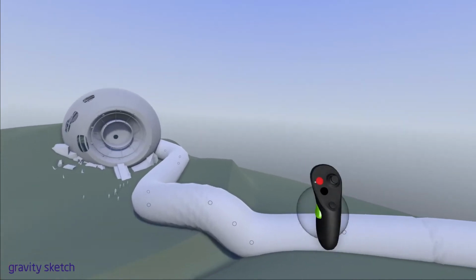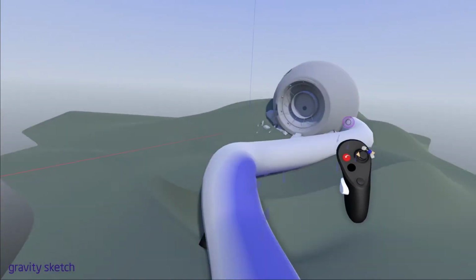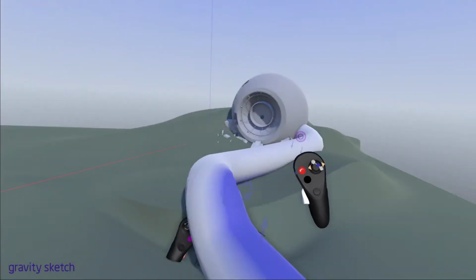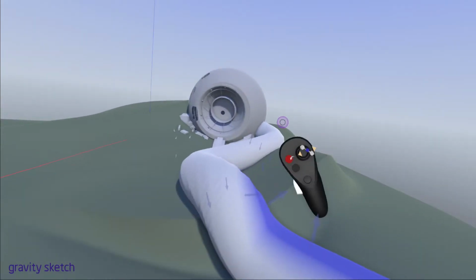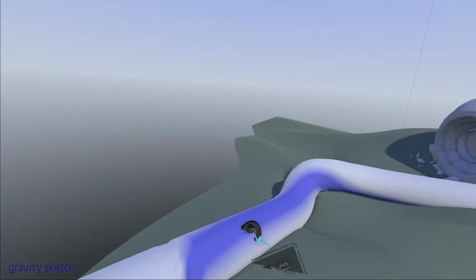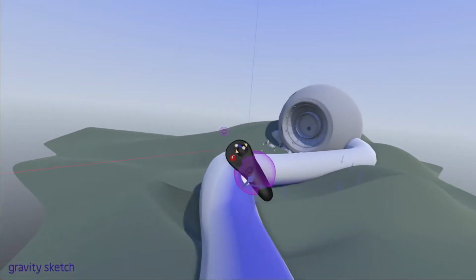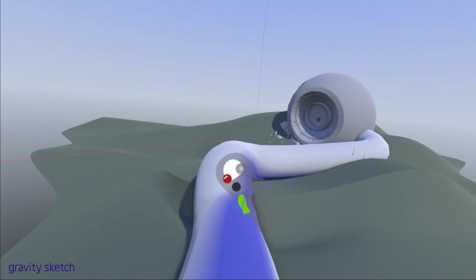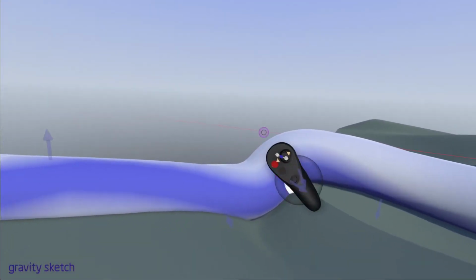Some of you may know that you have the ability to change the normals, or the twisting of the object, with these arrows. But one thing that we've added is this stripe that runs along our strokes to show us exactly how much is twisting, where it's twisting, and where the normals are. We can use that as a visual reference to loosen the tension in our geometry.